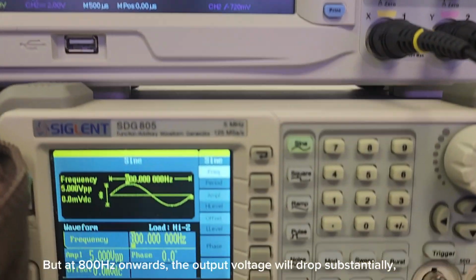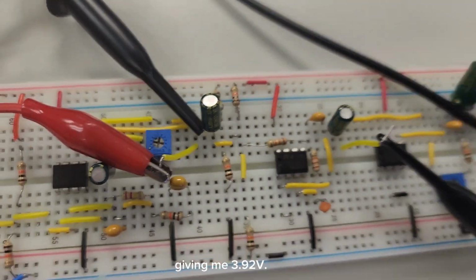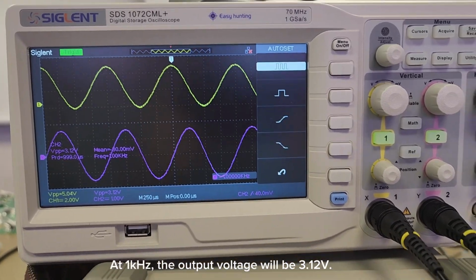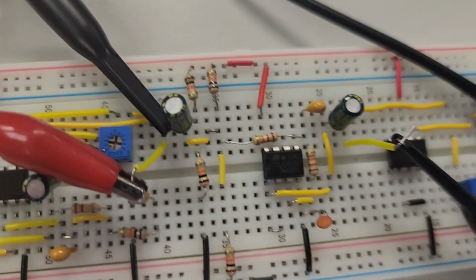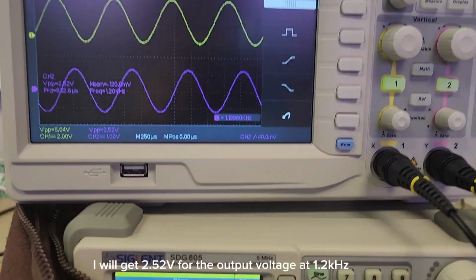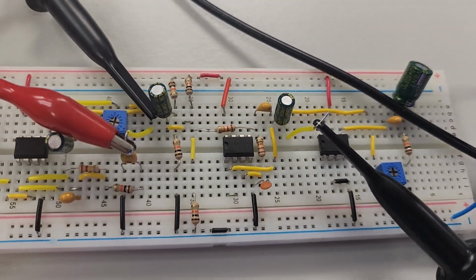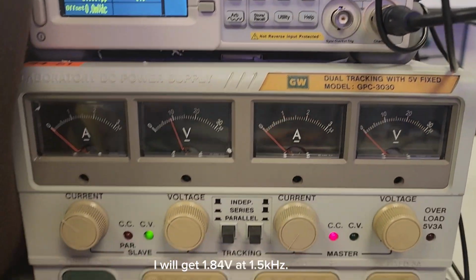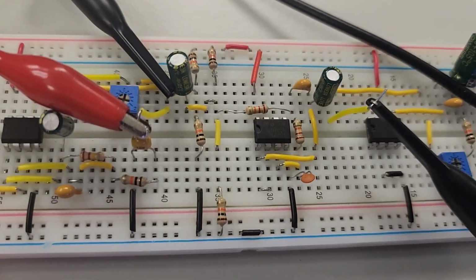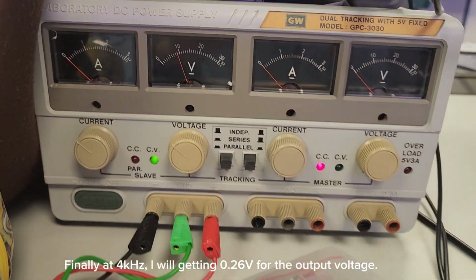But at 800 Hz onwards, the voltage output will drop substantially, giving me 3.92 volts. At 1000 Hz, the output voltage will be 3.12 volts. I'll get 2.52 volts for the output voltage at 1.2 kHz. I'll get 1.84 volts at 1.5 kHz. Finally, at 4 kHz, I'll be getting 0.26 volts for the output voltage.